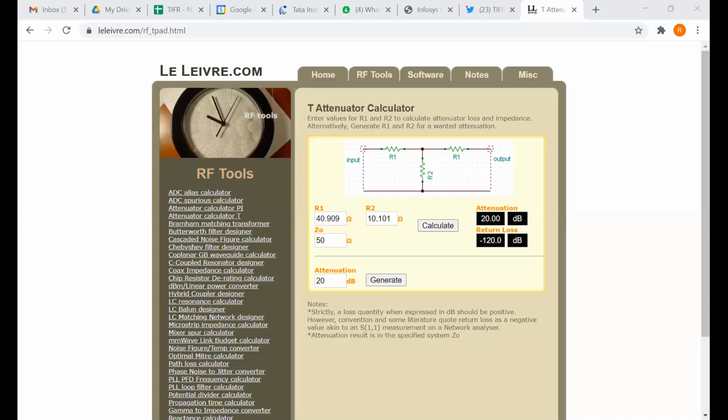Sorry, just to say this again. The practical point I was making is that if you have an attenuator sitting in the lab and you don't have a quick way of knowing what it is, you can just measure the resistance between the ground and the center pin. If it is closer to 50 ohms, then it's most likely a 20 dB attenuator.